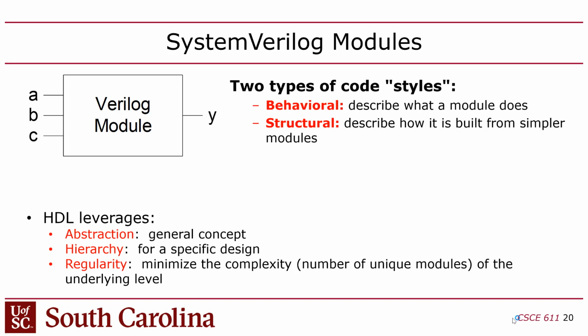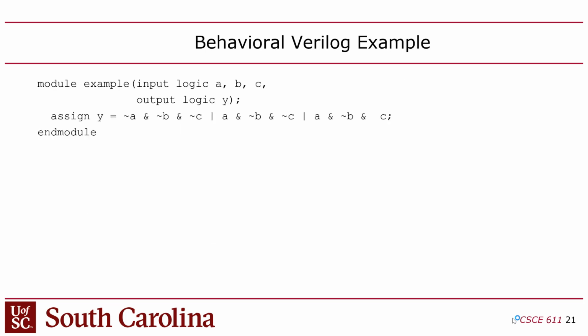Make sense? So what I'm trying to say is that a lot of the code you guys will write, most of it will be structural code, which will be basically instancing things and connecting them with wires and trying to reuse code as much as possible. Okay, so here's an example of a behavioral module. This is intended to introduce you to the syntax. The syntax of Verilog is different from anything you've seen before. It's not as unfamiliar as VHDL.